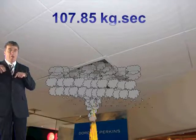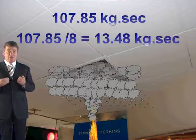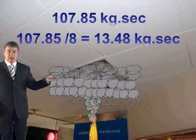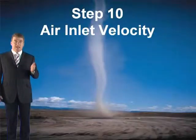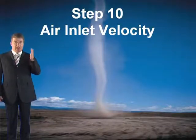If you divide that by your 8 ventilators, you're only going to get approximately 13.48. That is clearly much lower than the M-Crit. In other words, you are confident that plug holing is not likely to occur, and that covers that particular step. No plug holing.